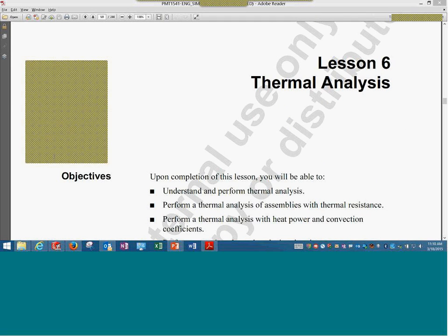Okay, what is the right time to use or not to use submodeling? First of all, please be aware of the limitations. Technically, submodeling is useful for assemblies only, not too relevant for parts. It is a huge assembly, and you observe high levels of stress present only in localized components. So it is far more relevant there.